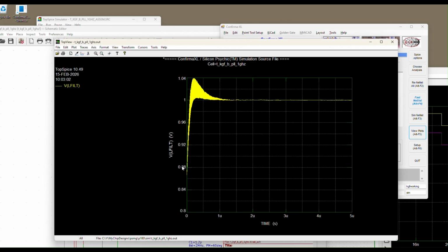And okay, so this is the capture and lock process for this behavioral phase lock loop. Now you might recall that we selected the VCO frequency to be 1 gigahertz, and it should be 1 gigahertz when the control voltage is 1 volt. So you can see that the loop has settled, had locked up with the control voltage at 1 volt. So this is a good sign. It means that it locked up correctly.